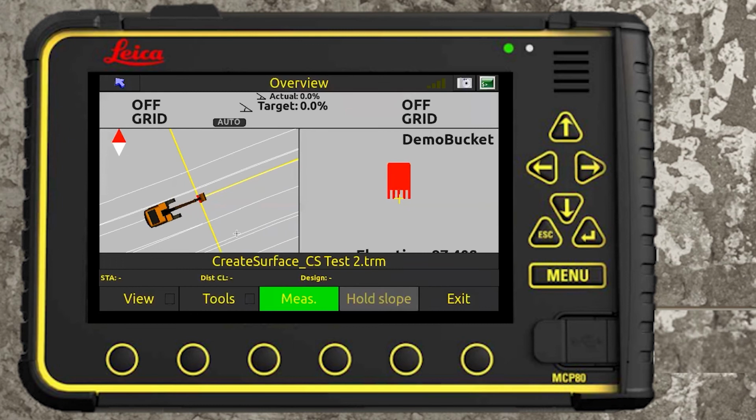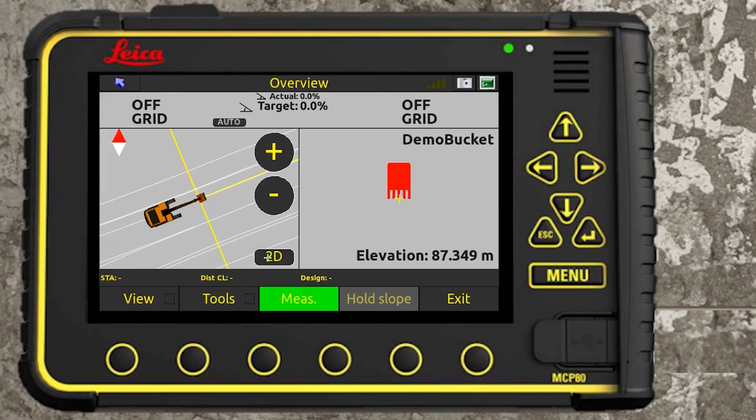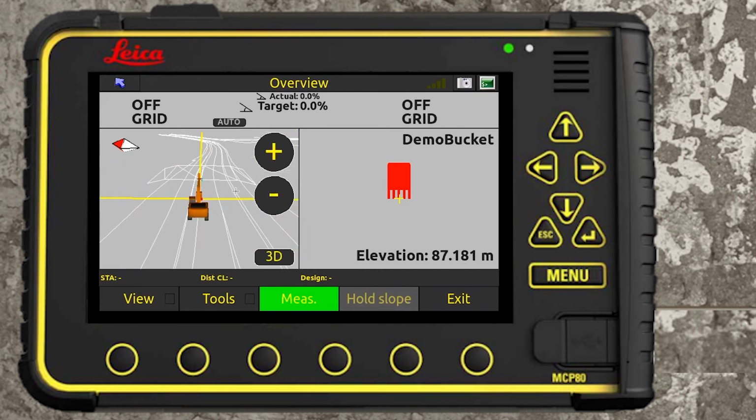Okay, enter, and okay. So that's going to load straight in, and again we just have to track down. So there is our model. You can see we're coming into it here now. So we have that 20 meter square level surface, and then we have this minus 25% slope, 5 meters distance out either side. Okay, so you see that coming in on the section view once we get over that model. Again, you have to be over it to show the cut and fill values.